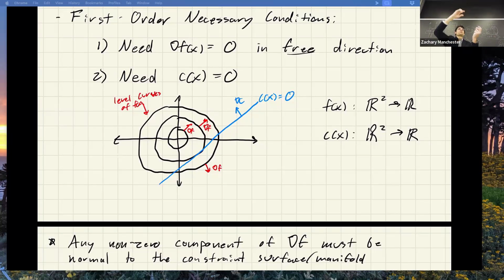The complementarity is 0. Basically, the height times the contact force, the normal force, has to equal 0. When your height goes to 0, then you get a normal force, and lambda is exactly the normal force. It's just saying that the floor can only push up on the brick. It can't pull down. So you get this very nice intuitive picture, and it's on your homework, so you should check that out. For me, that's the right mental picture. You're thinking about contact force and gravity and F equals ma, and it's super clear in your head. Complementarity in that context is literally that you can't have force at a distance. You can only have force when the things are touching each other.